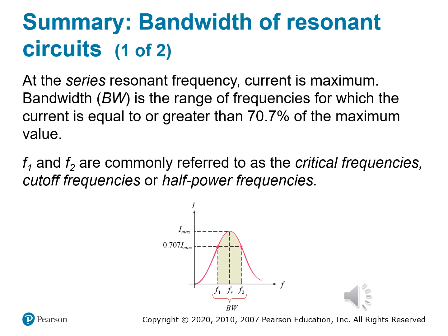So not being at one specific frequency, but a frequency range where you get the not ideal, but the best before you drop to 50% of the power. So f sub r, don't forget that, that's right in the center. So the bandwidth being equal to f sub 2 minus f sub 1, that's just going to be the difference, the total length between those frequencies. Again, that's a spread where your signal is strong, clean, effective.